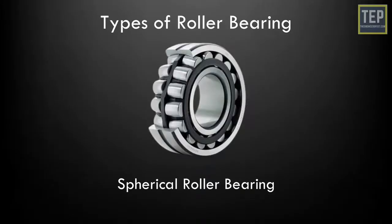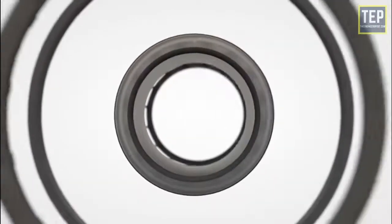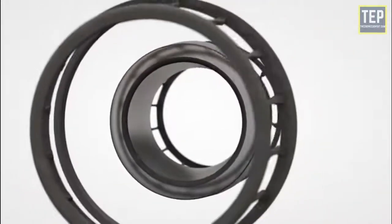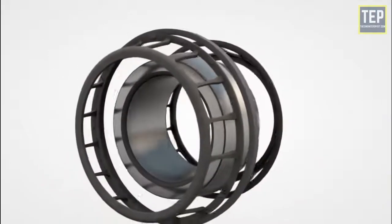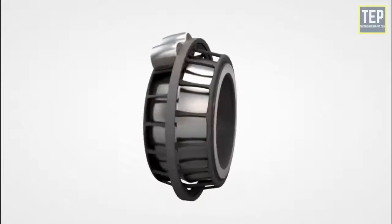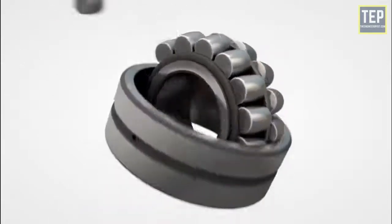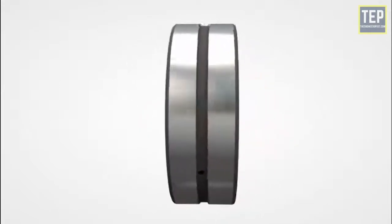Spherical roller bearings. These bearings are very robust and work on the same principle as self-aligning bearings, with the exception that they use spherical rollers instead of ball rollers, allowing higher loads to be supported. Spherical roller bearings are suitable for absorbing high radial loads and moderate axial loads.